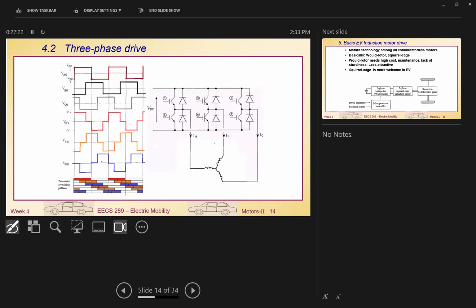So that means for a 3-phase motor, this one of the display shows how we can use a simple, non-PWM waveform to excite an AC motor. Assume that's our AC motor, and we connect them in 3 phase. We can use PWM as I showed you just now, but 15 years ago, when we didn't have PWM technology, we only used really slow frequency to drive an induction motor.